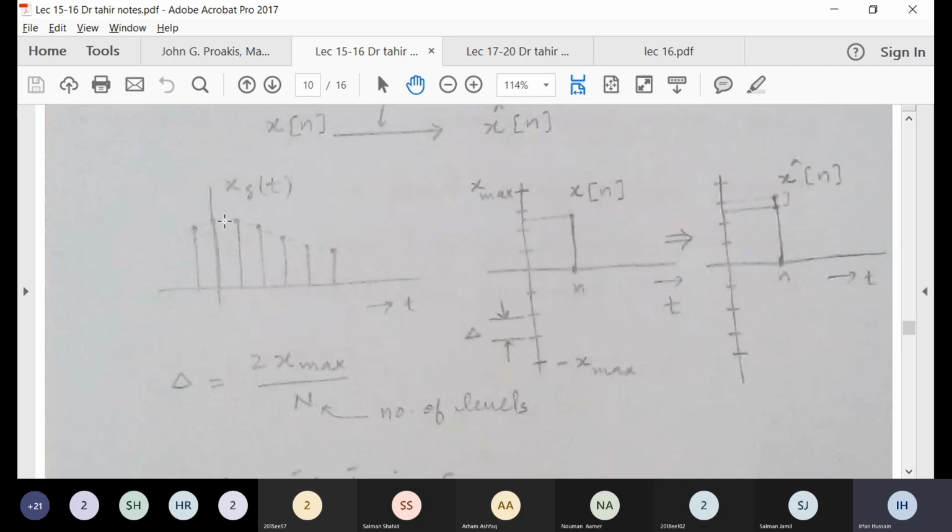So you can see here, this was your sample signal. This is just the PCM we have just discussed, and it is a pictorial description of pulse coding. These are your continuous values; amplitudes could be continuous, and time is discrete here. Every value will lie within a quantization region, but for this quantization region I will take only one value. So let us say this is the value x tilde, and this will be the amount of error, which we have denoted by x minus x hat, where x hat is the quantizer output.